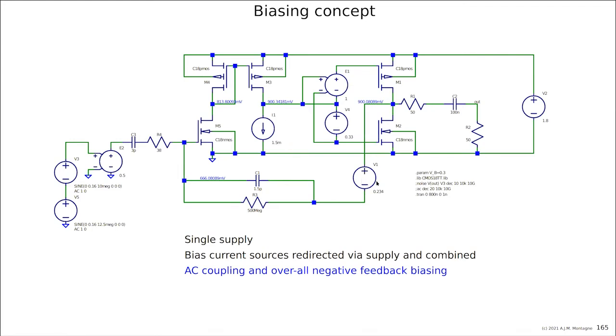A similar thing can be said here. If this is a voltage source, say the impedance of the voltage source is large, maybe at high frequencies, then this impedance will definitely be part of the transfer, because the transfer was set by C1. So in order to have more budget for the impedance of V1, I might as well tie this side of C1 directly to the output. That would be better. Then I have more margin for V1.